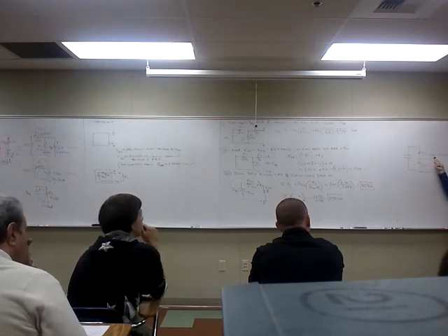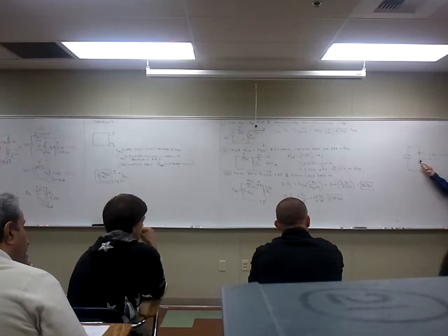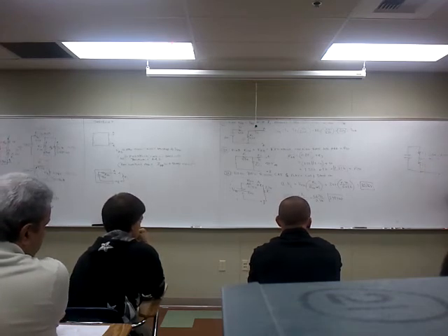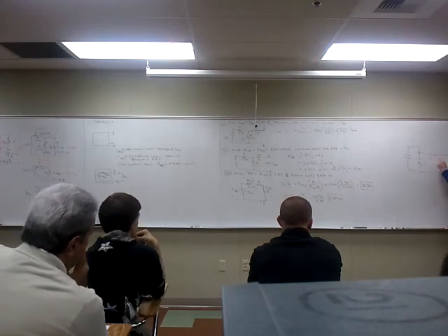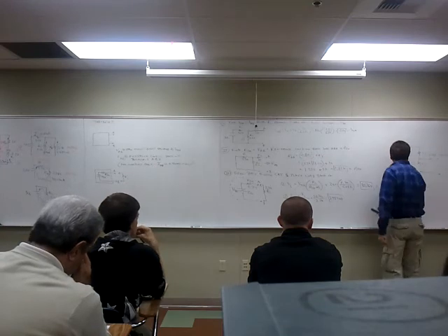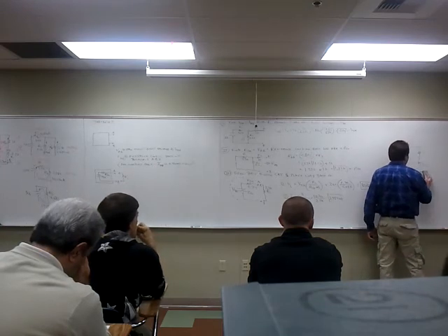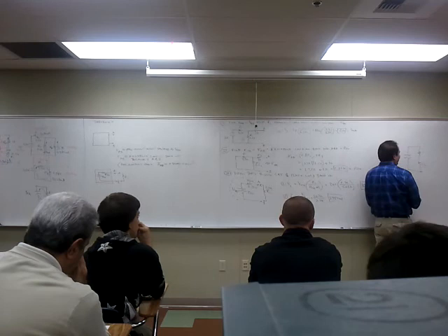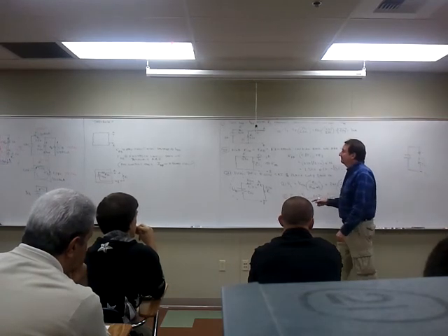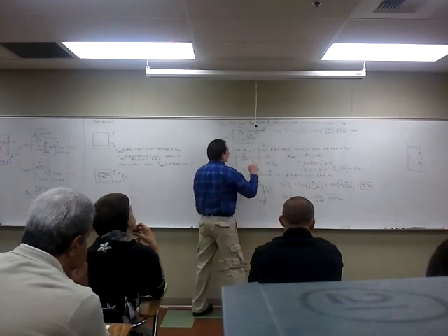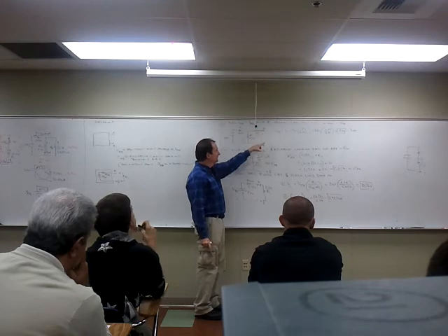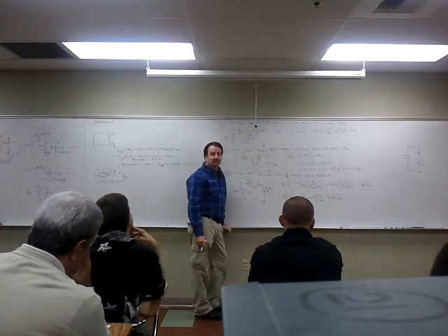No voltage here, yet there's still a connection. No voltage across, but this point's identical to that point. So no difference is the same. This point is the same as that point. Therefore, if that's true, the equivalent circuit is this. Isn't this equivalent to having A here and B here? That's the equivalent circuit of this. A is really that point if no current is flowing through that resistor, and B is really that point in terms of measuring voltage.